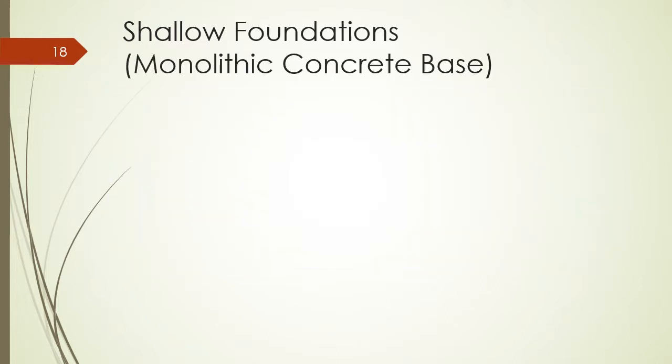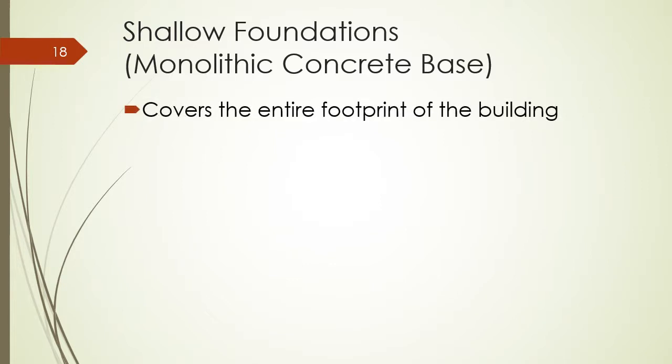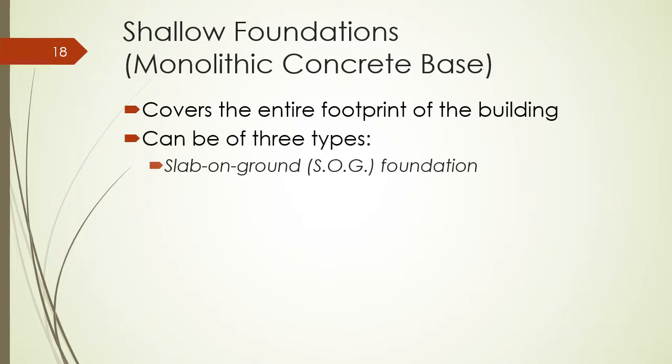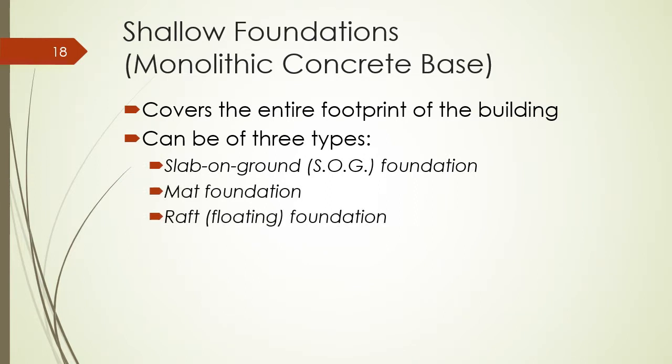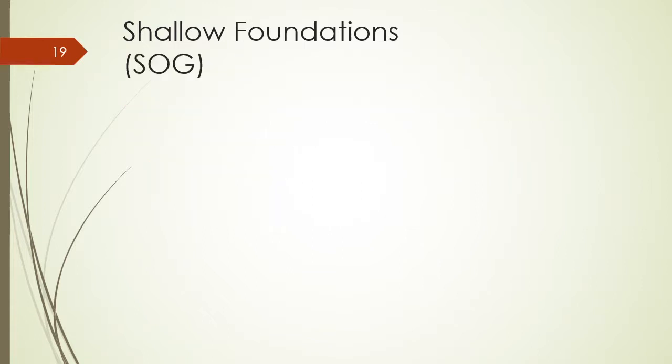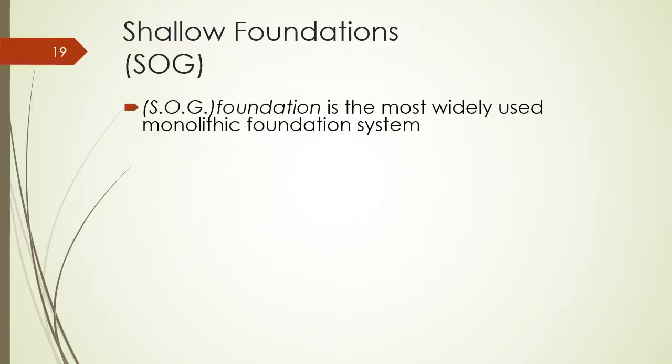When we're talking about monolithic concrete bases as a shallow foundation, these cover the entire footprint of the building, and we have three types: the slab on grade, the mat foundation, or the raft or floating foundation. The slab on grade is the most common type of foundation system.